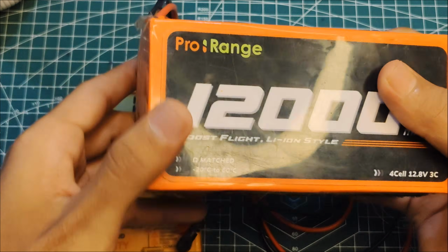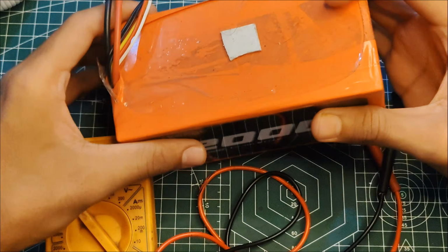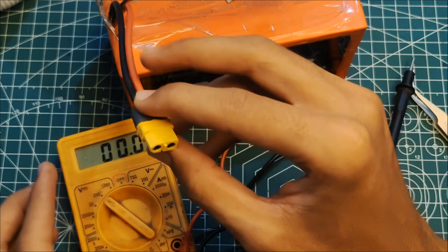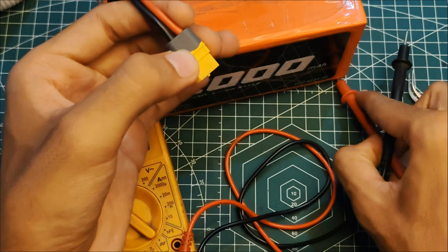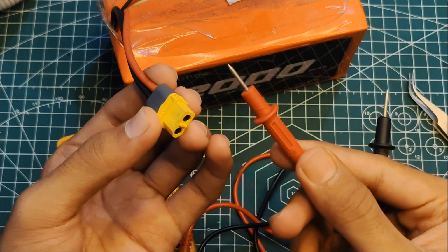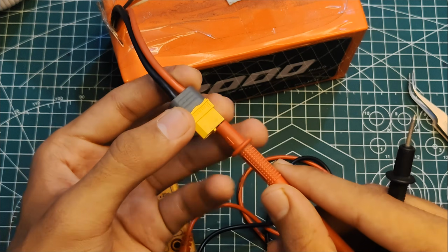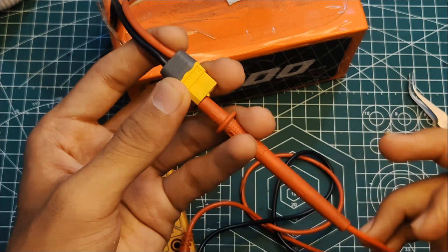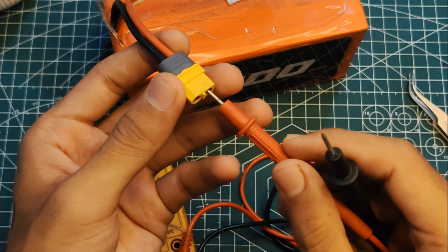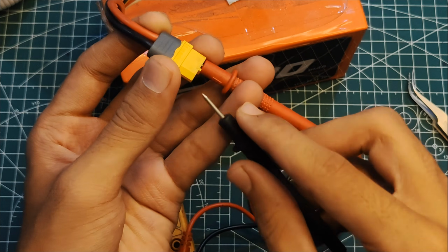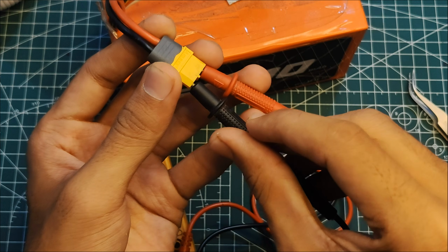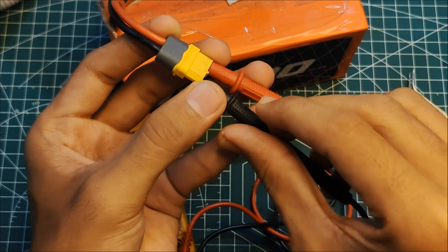So I have this lithium iron phosphate battery, and I have this terminal at the end of it. Let's try to check what the voltage value of it is at this point. What I have to do is put the red probe in the red terminal. You can do the opposite also, but the values would be on the negative side. So I need to put the red probe into the plus terminal, and the black probe into the minus terminal.